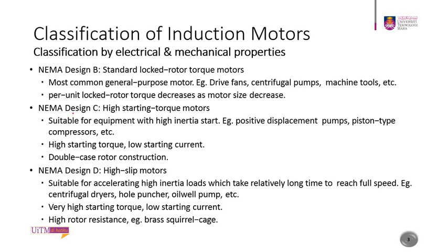Then you have the NEMA design C, which is for high starting torque motors. It's suitable for equipment with high initial start, for example positive displacement pumps and piston type compressors. It has high starting torque but low starting current, and it uses the double cage rotor construction.